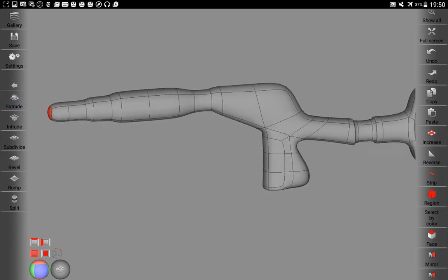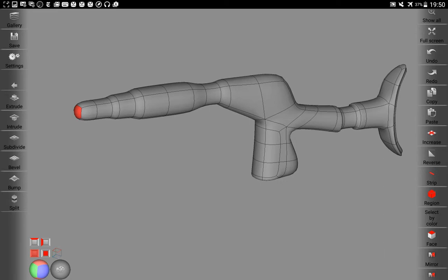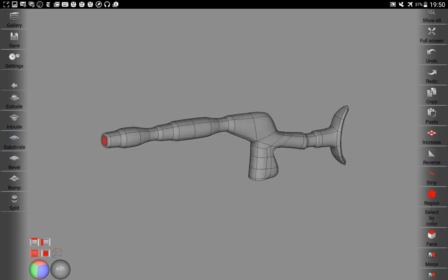So step by step we'll give it a little bit of... you see what you can do. You can just transform and scale it all the time with the scale all command, and it always follows the barrel direction, smooth and round. And then we use the subdivide command and extrude it and subdivide it.